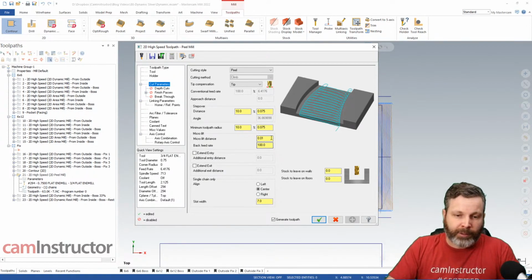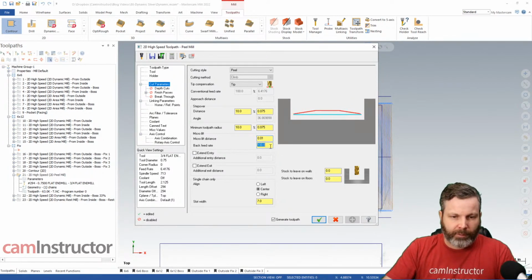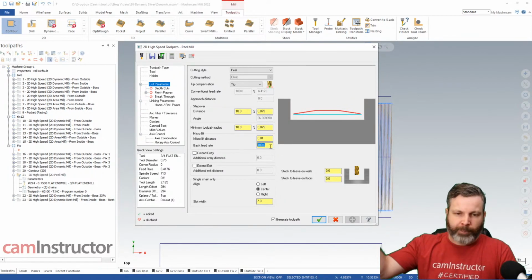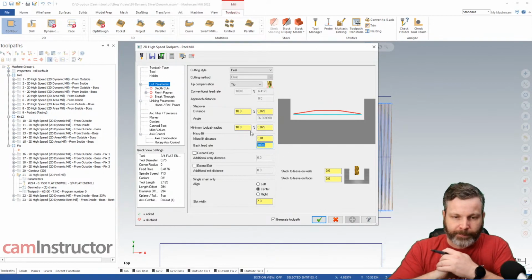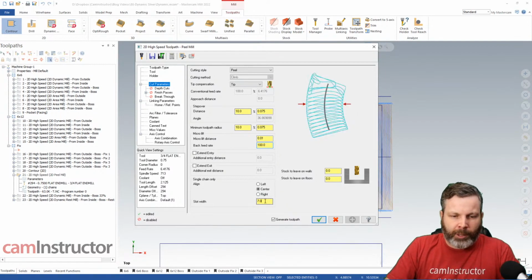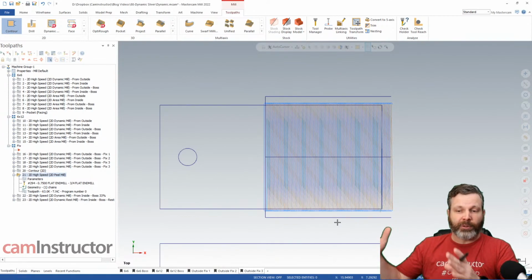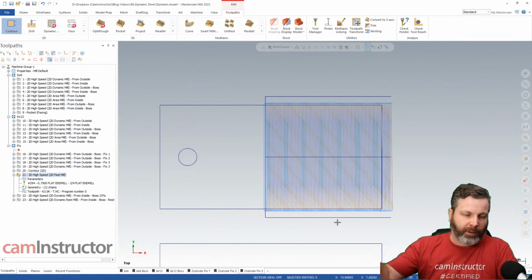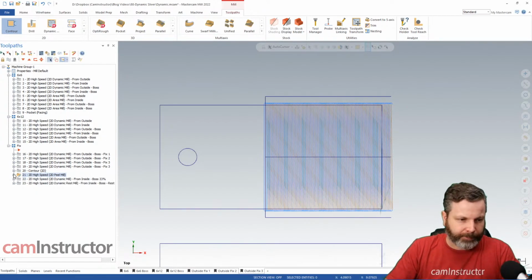I've also got the option here for micro lifts and repositions. Instead of retract, rapid, over and down, I can control it with micro lifts, so that's an added benefit. With this one as well, it's easy for me to change the width. I can extend or shorten if needed. So peel mill, another good idea to chop off that long side of the part in order to get dynamic mill to work better on the other half.